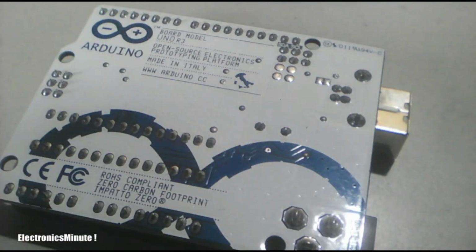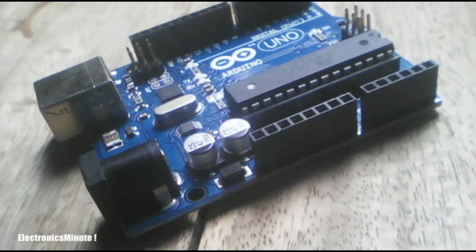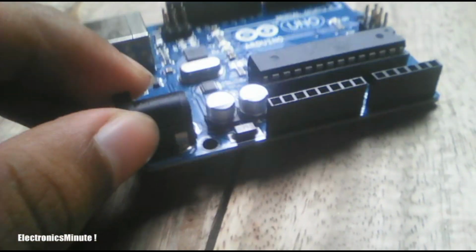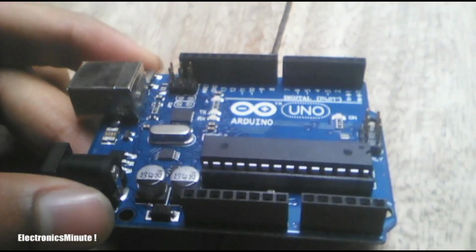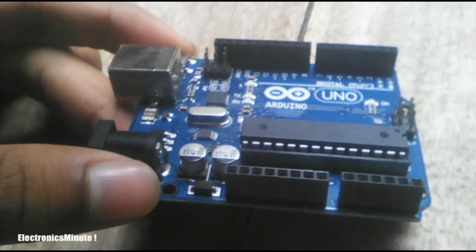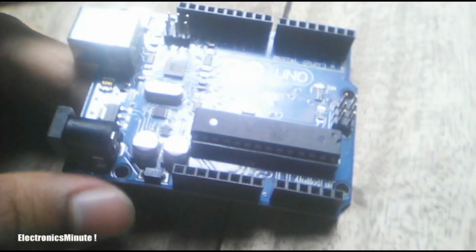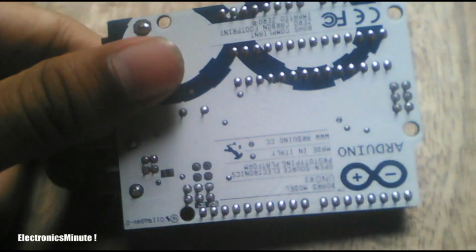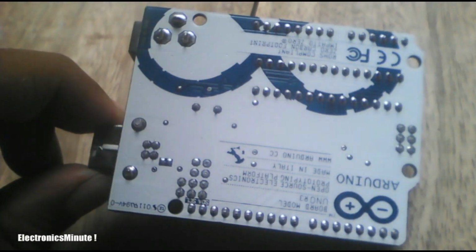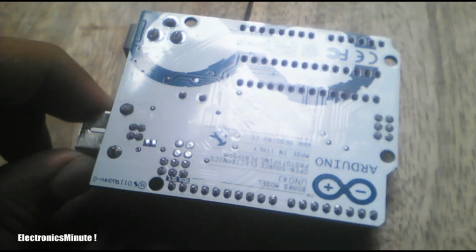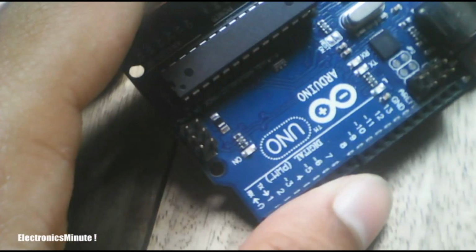And if you don't know what an Arduino Nano or the other types of Arduino boards are, in short they are called microcontrollers, based on Atmel Atmega 328P or 168P microcontroller ICs surrounded by some electronic components, with extended pins from the IC, creating an electrical circuit that performs arithmetic and logical operations based on the instructions given to it by programming with the Arduino IDE, at a certain speed, in this case 16 million operations per second or 16 MHz.